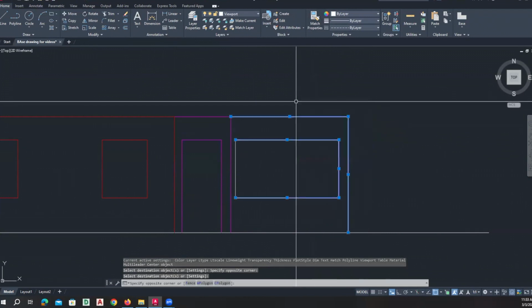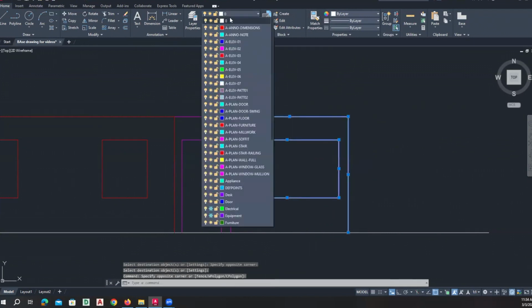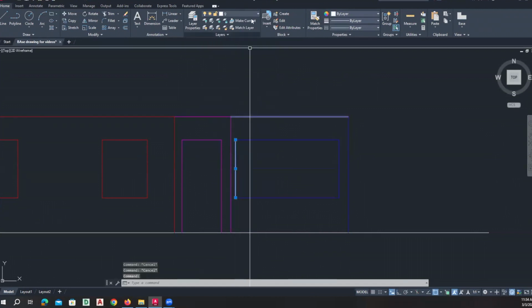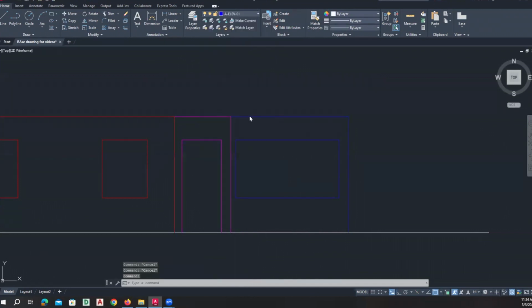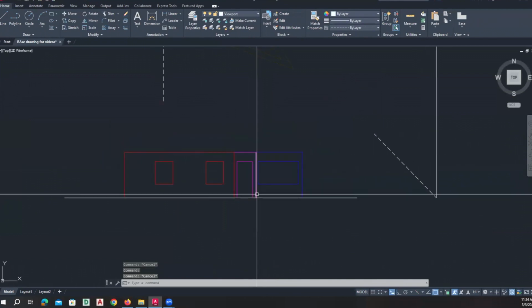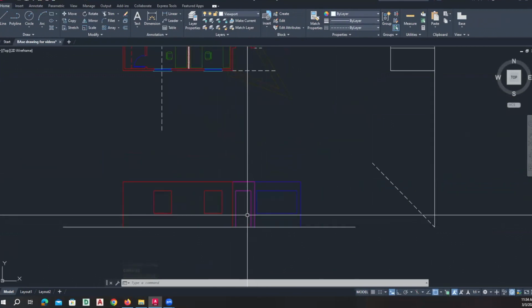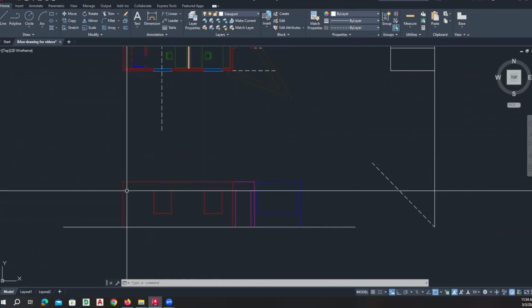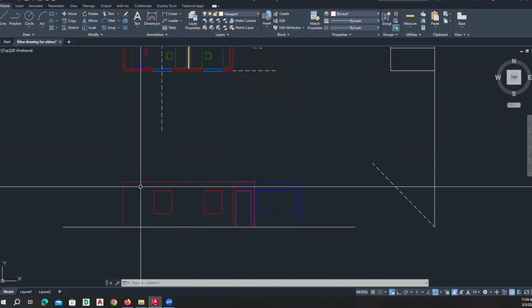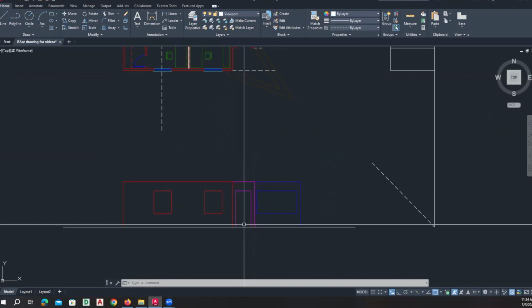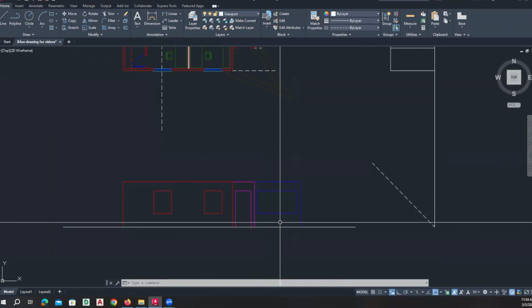This door will be on that same layer because it's in the same plane, right? And this window, this side of the wall, that will be on the next lightest, which would be 01, right? Same thing with this one, 01, okay? So now I know it looks, the multiple colors here, but if I were to print this, you would see that these lines that are closest to me will print darker. This will be slightly lighter, and this will be slightly lighter, okay?